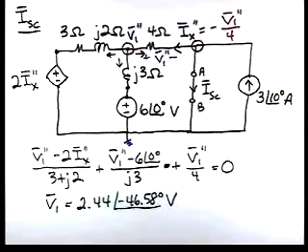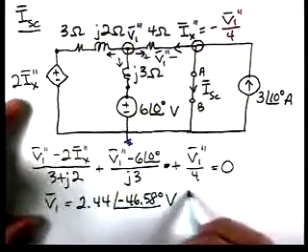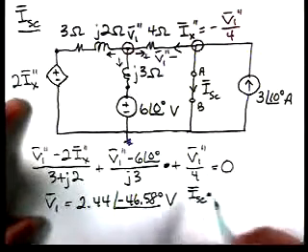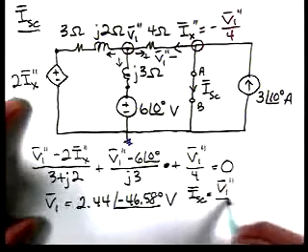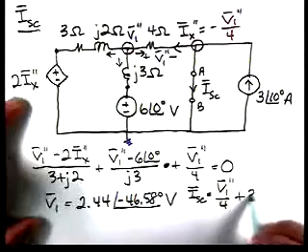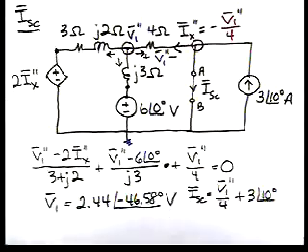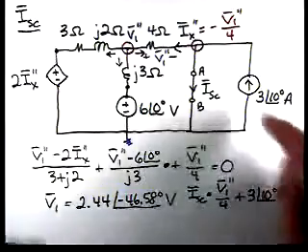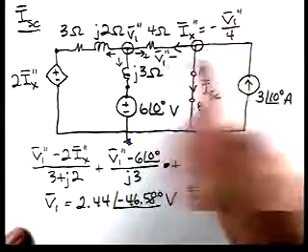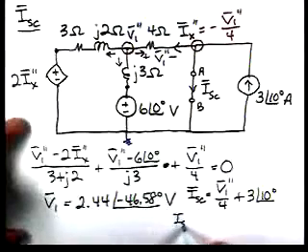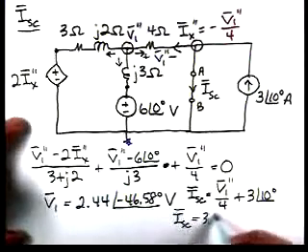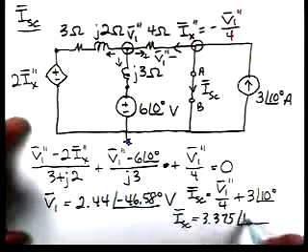I short circuit is leaving the node, 3 at an angle of 10 is entering, and V1 double prime over 4 is entering. If we calculate, I short circuit turns out to be 3.375 at an angle of 1.33 degrees.